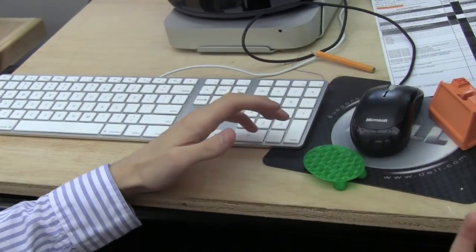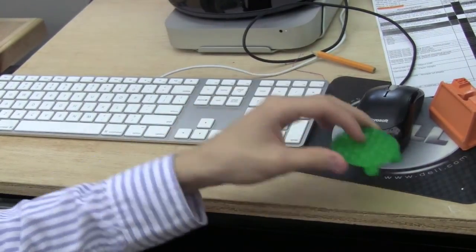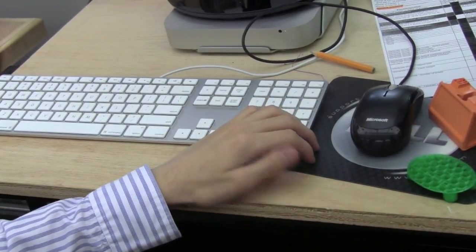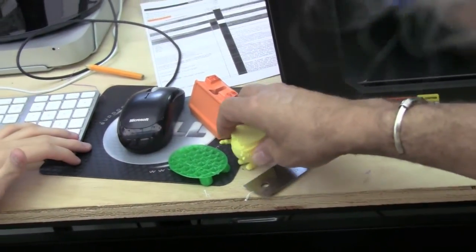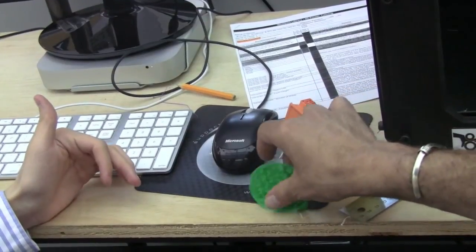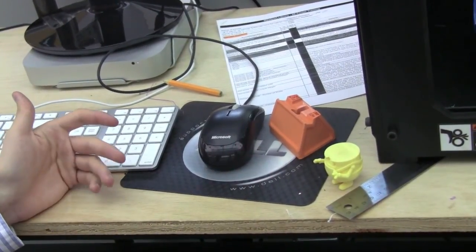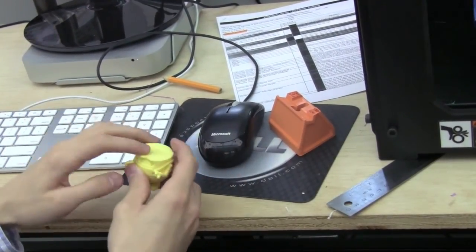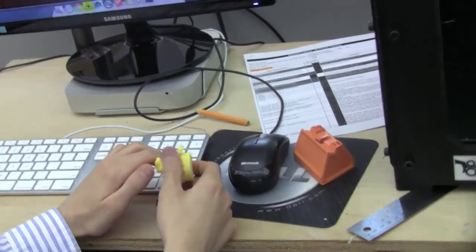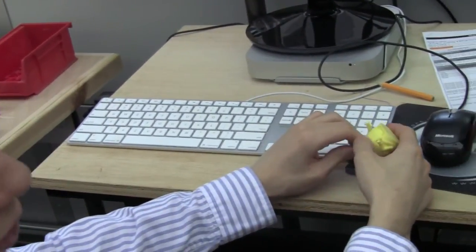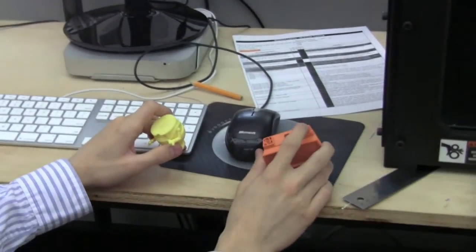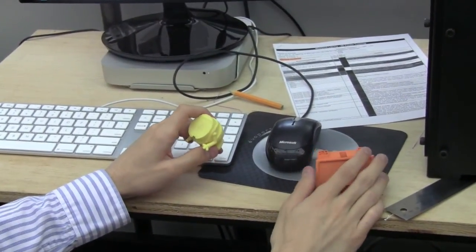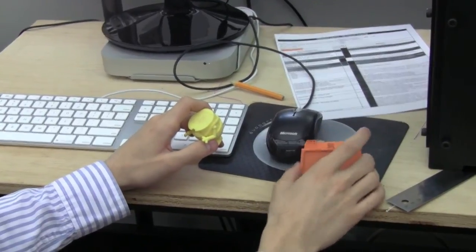So you can also feel how dense it is. This is much heavier than things with infill. Right, exactly. So it's up to you, really. If you need something that can take a hit, then you would use 100% infill because this is very, very solid. And maybe if you just want it to be heavier, like for example, this is a phone stand, and you might actually want this to be 100% infill if it's holding a phone, so it doesn't move around much.